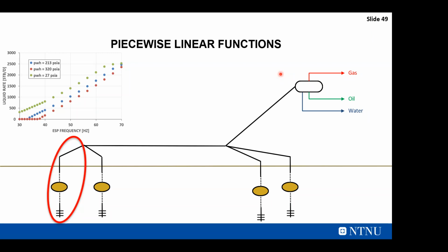Yeah, I think that using both the diluent and the ESP frequency, we can generate the results using the model. So we can use that data. We generate different models, and once we generate them, we can train a neural network to take care of that domain, and then we can do the stochastic optimization. When we do the stochastic optimization, it can solve it in a few seconds, I would say 20 to 30 seconds, and it can give you the global optimum for both values, taking into consideration the model data that was used to train the neural network.